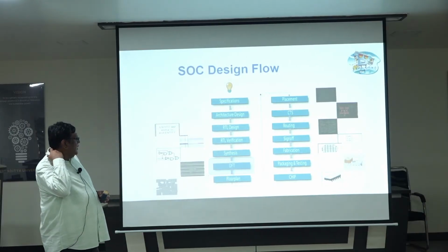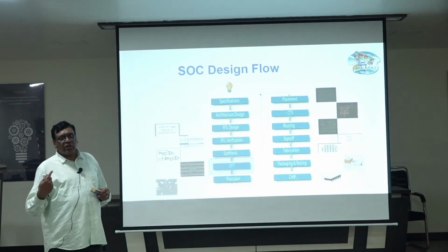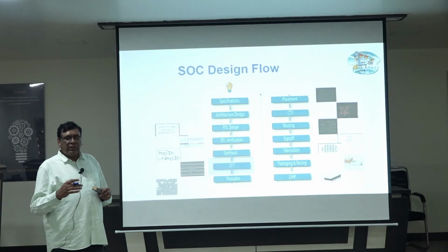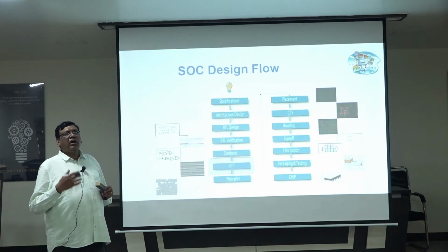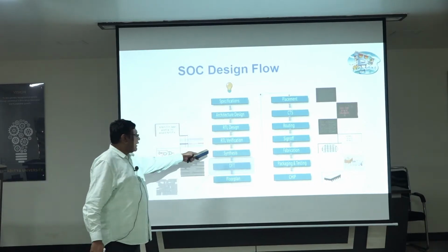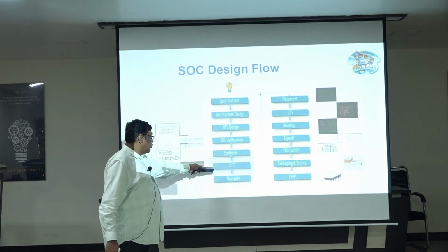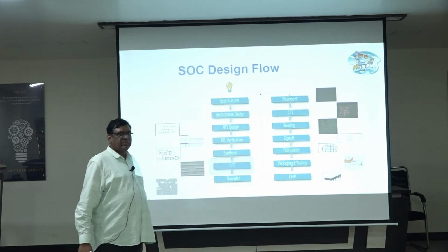Then comes synthesis, which converts the design into hardware, not directly hardware, but what gates, what transistors, what flops we need, and all those things are produced after synthesis. There the question of DFT will come. Most of the DFT role happens after synthesis.